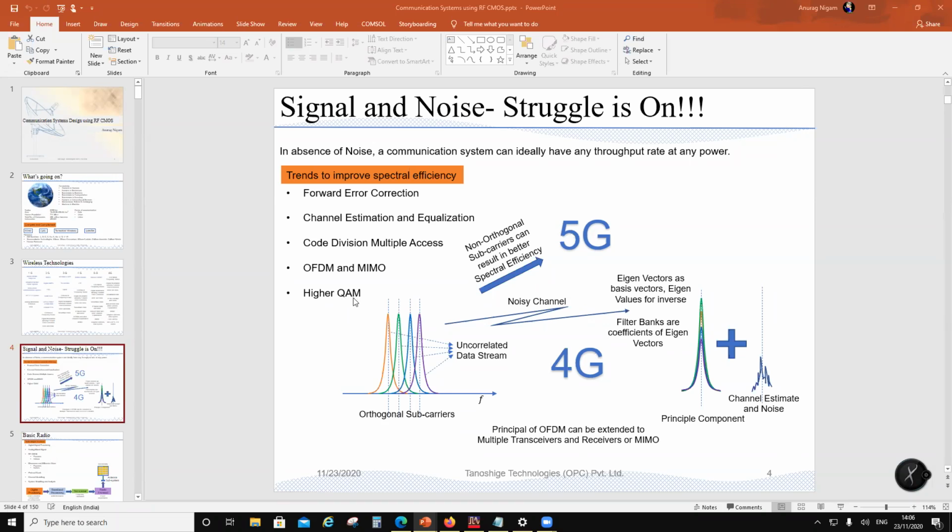And then they realized that if you do a very sudden transition in phase, the bandwidth is going to increase. So to minimize bandwidth, they said, I'm going to use 2 QPSKs which are offset by 45 degrees. Then that became differential QPSK, DQPSK, right? After that, they said, okay, now let's see if I can bundle 4 bits together.